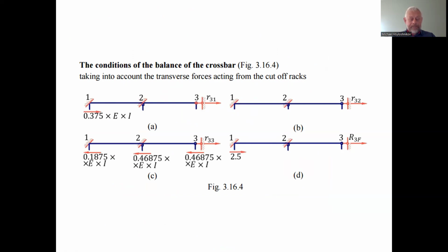That's why, if we have the translational displacement on the first one, we have to find not the bending moment, but the force. We adopt the assumption that within the displacement method we do not consider the action of longitudinal forces on the change of the length of the elements of the mechanical system.